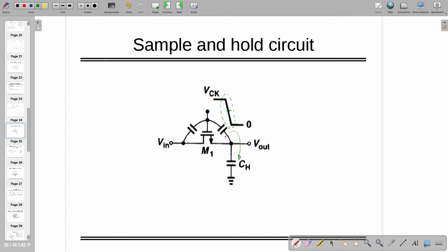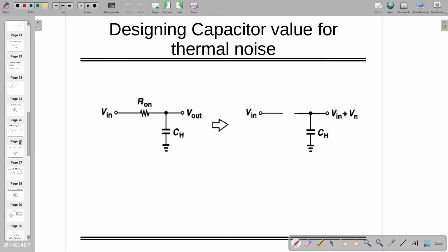that charge will be dumped here through a capacitor. Same thing is going to happen here also, but as the previous circuit is a function generator connected to 50 ohm, no problem. But if it is connected to something else, this is a problem again. It will be again reverse side, you will observe such a thing. This kind of phenomenon is known as clock feedthrough. So your clock is getting back to the node.